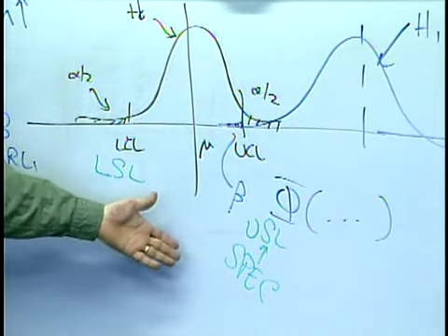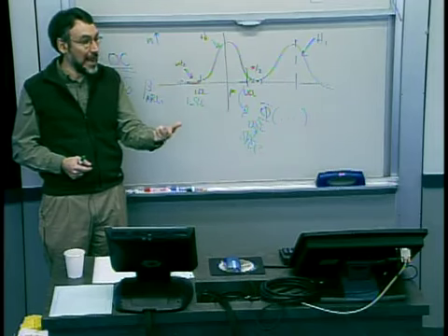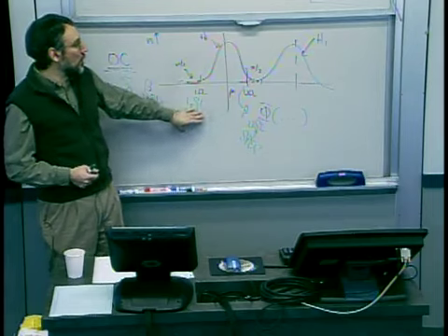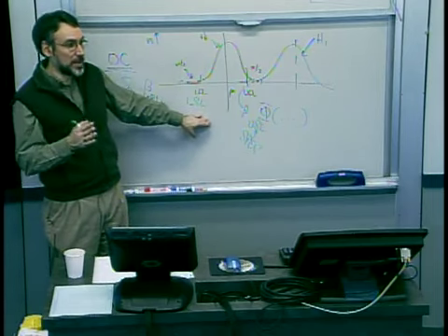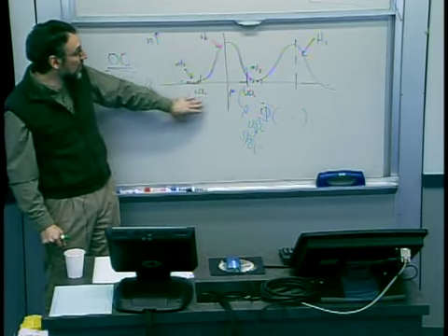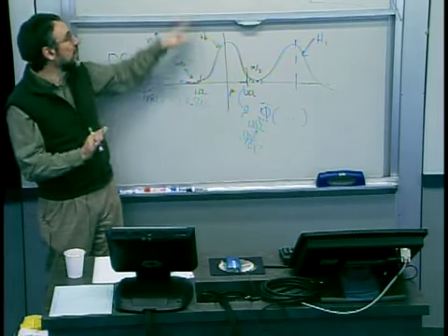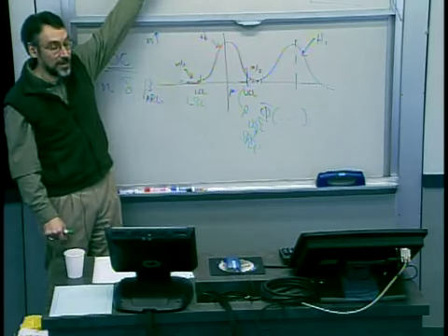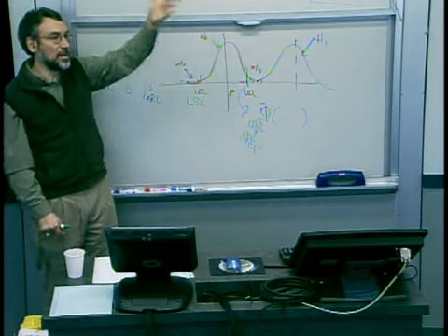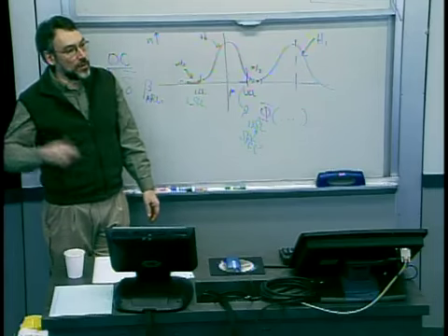And so nominally, your spec limits wouldn't actually change if you're changing sample size, right? The part still needs to function correctly within a certain band. So in that case, you change sample size, your spec limits would not. But what people often do is erroneously set the control limits to equal the spec limits. And that's wrong. What you want to do is set the control limits based purely on the statistics based on your false alarm rate: the chance of observing, by chance or by random probability, an unusual event.